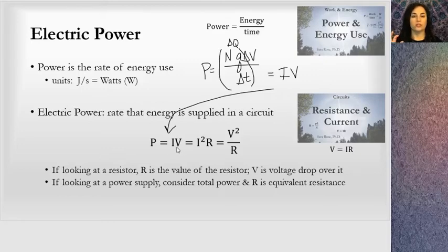That voltage difference, remember, is a difference supplied by a power supply or over a circuit element. There's a voltage difference, but in these equations we just represent it with a letter V. So it's a little sloppy, but remember that concept is in there. And using V equals IR, Ohm's law, we can rearrange this into different versions of the same equation, and any of these is an equivalent use of this equation. I recommend using the version of it with the quantities that you have given in your circuit or can find